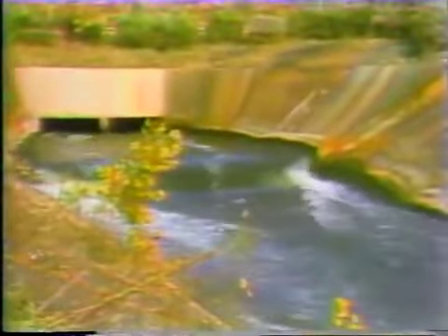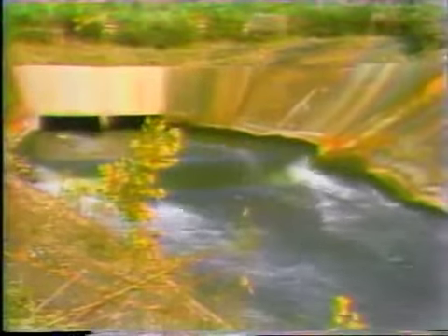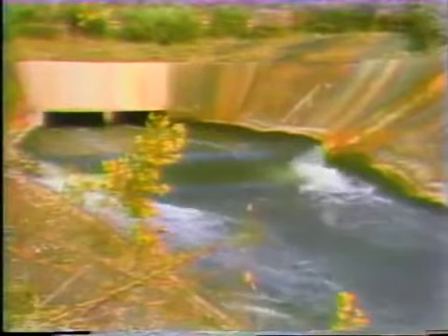Heat released into a lake, ocean, or river can raise the water temperature. If the temperature gets high enough, it can affect animal or plant life in the area. Now, the amount of heat that can be released into a body of water is restricted. At times, you may adjust load on your plant to control the amount of heat released in this way. Part of your job as an operator is to monitor the condenser outlet temperature and to maintain it within the limits prescribed by your plant's operating procedures.